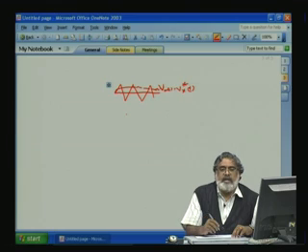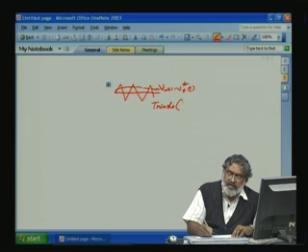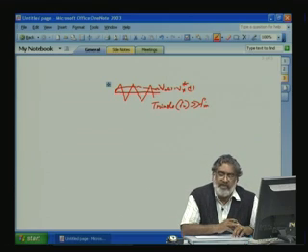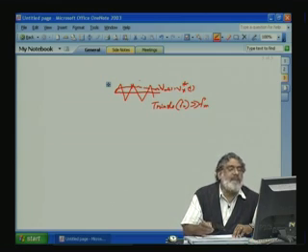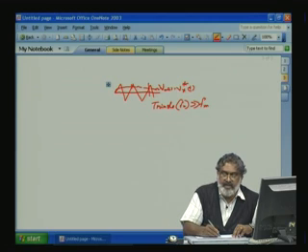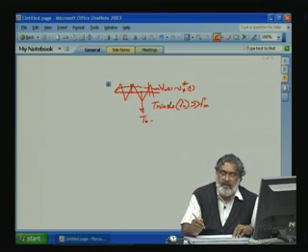So, for instantaneous control, the control should be as fast as possible. The frequency of the triangle waveform should be very high compared to the frequency of the sine wave. Okay, that is one thing, but here this is not true. There is always a delay in control. That means, once a comparison happens here, the next comparison happens here. So, we have a delay of TR in control.